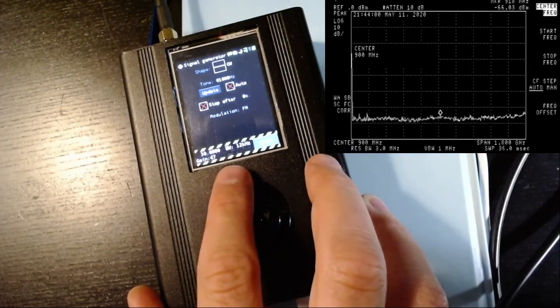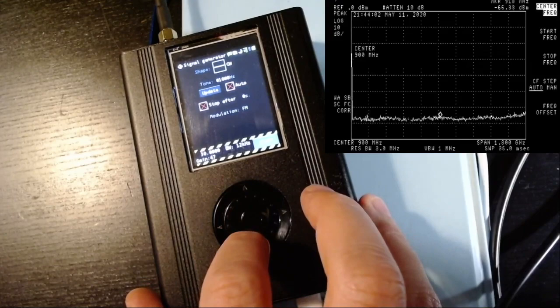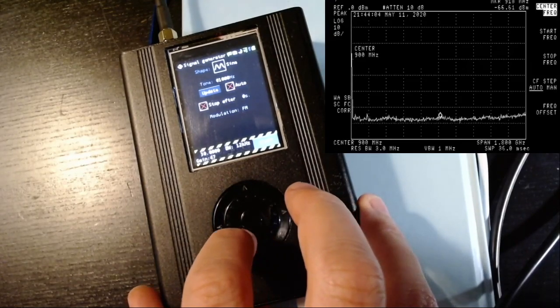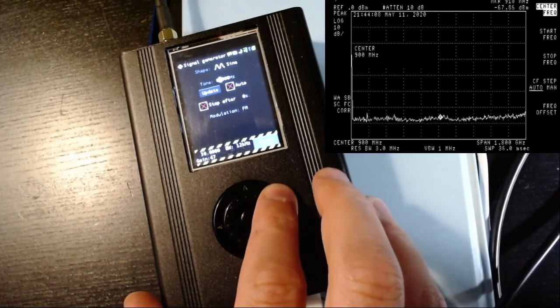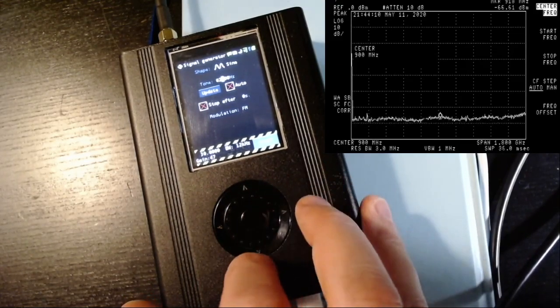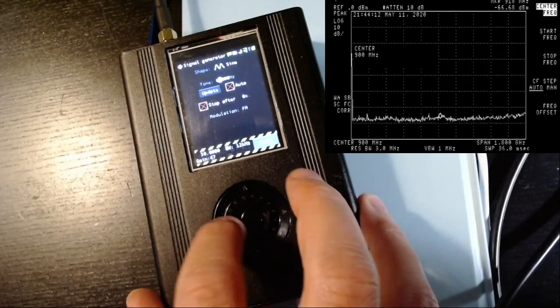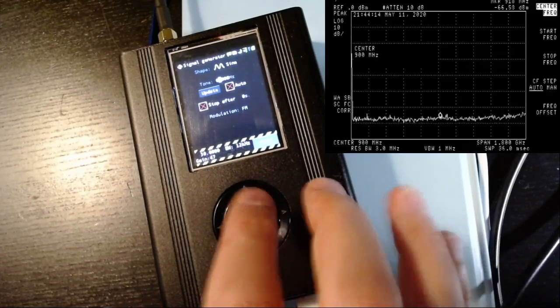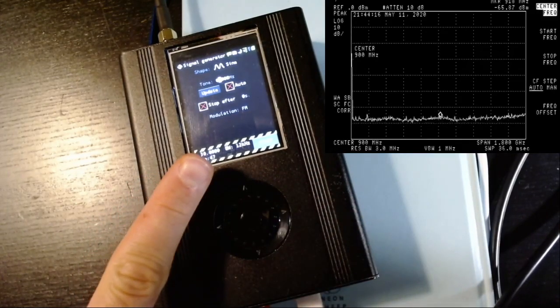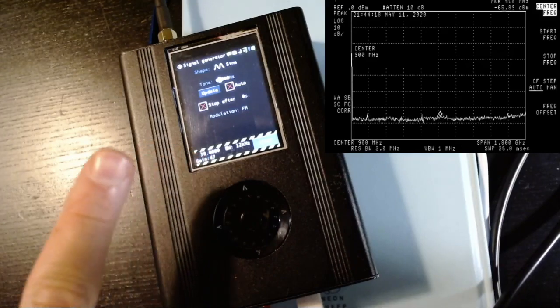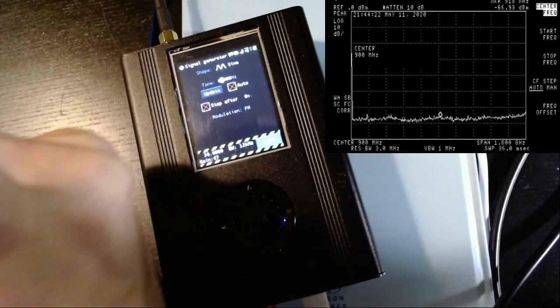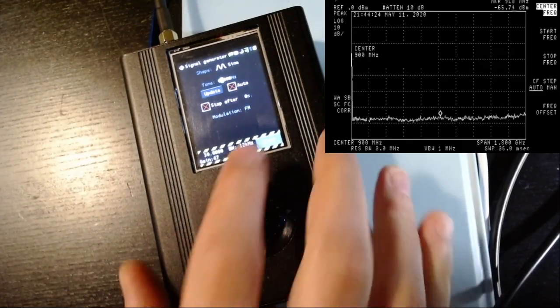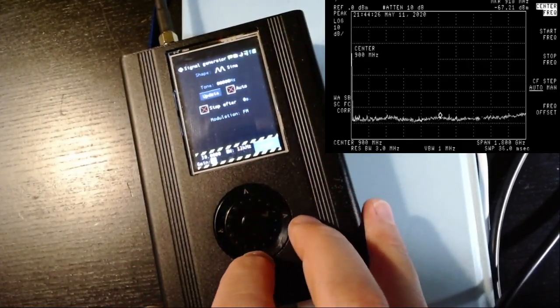In this application I configure the shape of the signal to be a sinusoidal function, and the tone to be transmitted to be 0 hertz. So this signal generator is an FM modulator. If we modulate no signal, so 0 hertz, we are going to get just one stable frequency at the carrier. The carrier is set here.